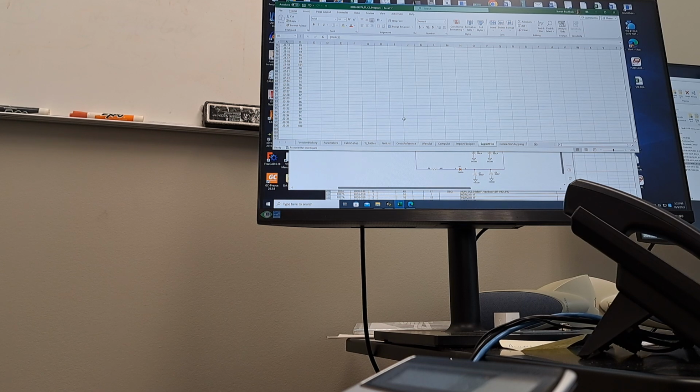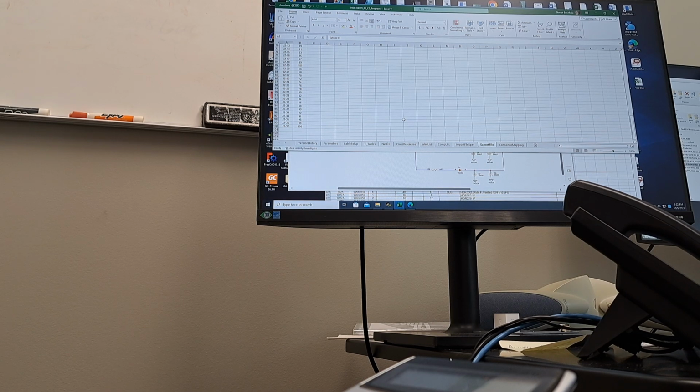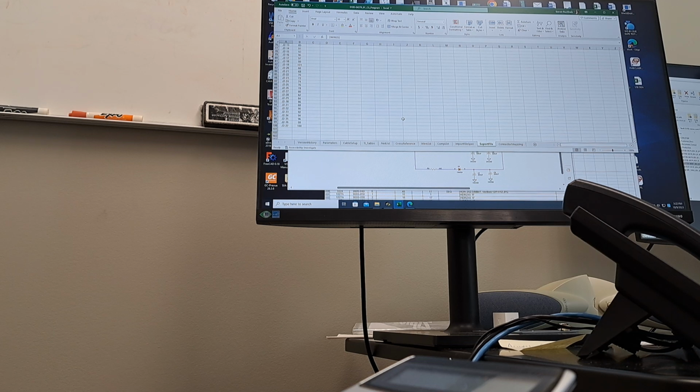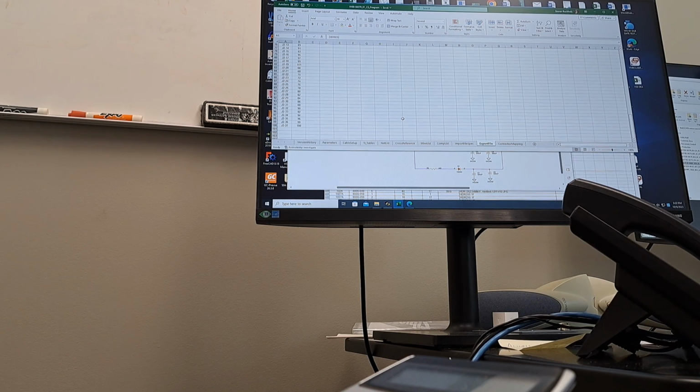So you'll see, like Danny and the guys in test, they don't necessarily think of an open as a big deal, it just kind of happens. It's just life. If we were doing a better job of making sure our adapters all worked, there wouldn't be any open pins. When it says open, it's not telling you that there's an open on the board that you're testing. It's telling you that there's an open between the pin that's plugged into the board, the adapter, and up to the cable scan machine. That's where the open is.